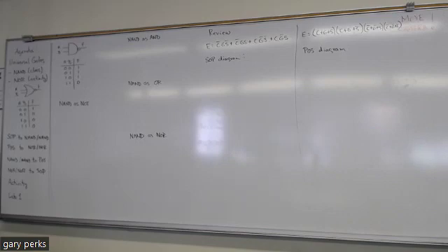And remember, those equations came from the same truth table, so logically they're equivalent. So one of the things you're checking for when you're doing lab 1 is that both outputs are giving you the same output for each of the 16 combinations. So the outputs should be in sync with each other.